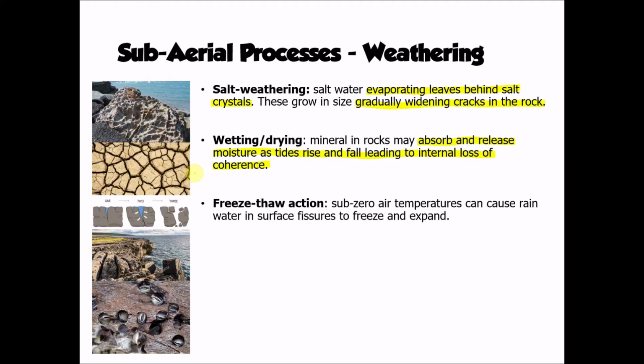A process of weathering you're probably quite familiar with, the process of freeze-thaw action as well. Any water that is in the cracks in the rock as a result of maybe rainfall or spray from the seawater, if the air temperature drops below freezing, that water is going to freeze and it's going to expand. Water expands when it freezes, and that is going to put pressure on the cracks or weaknesses within the rock. And over time, that is going to cause that crack to expand.